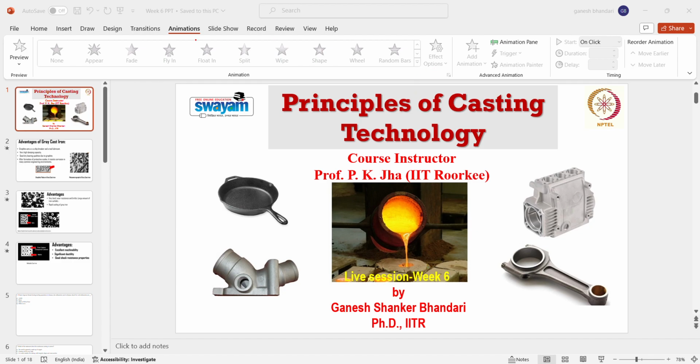So in the annealing process, we are providing both things: time and temperature at the same time. That carbon is going to diffuse out from this Fe3C system and get converted into 3Fe plus carbon. As we have already discussed, white cast iron decomposes into free carbon and iron as represented by the reaction, and it creates the malleable cast iron during that annealing process.